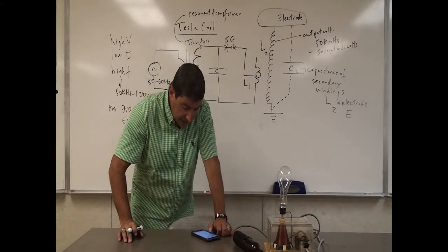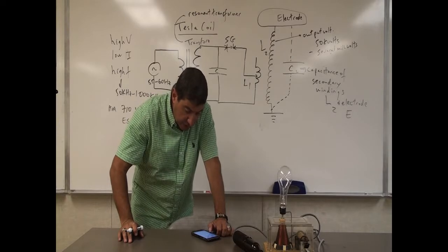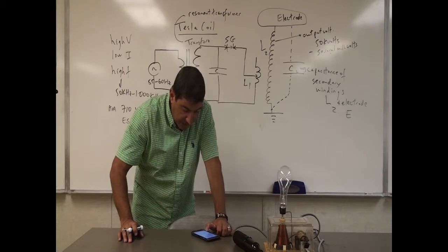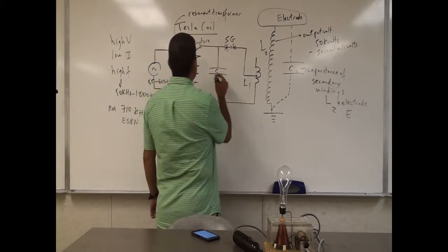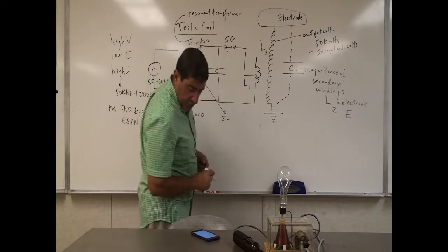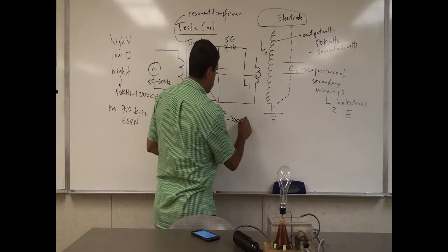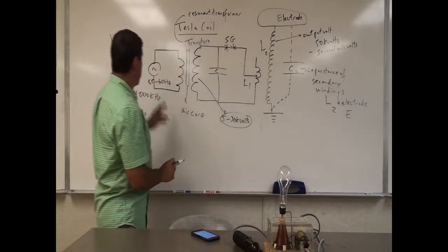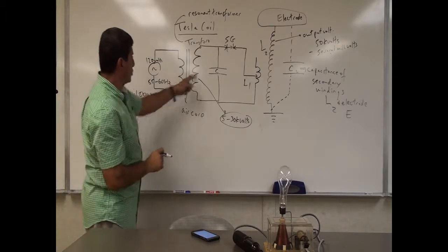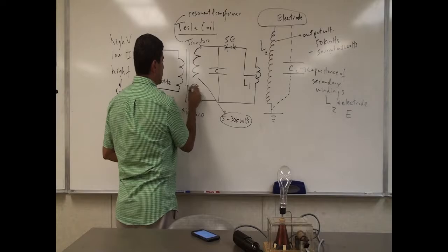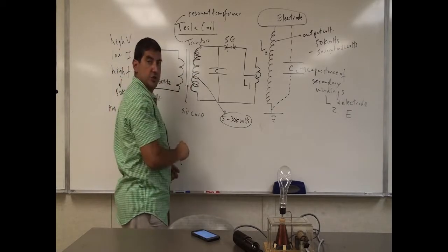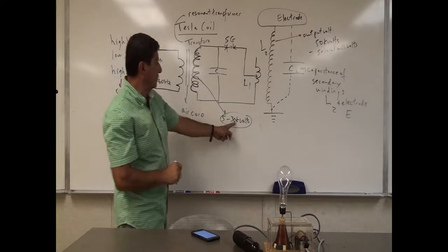So it says a high voltage supply transformer to step the AC main voltage up to a high enough voltage to jump the spark gap. Typical voltages are between 5 and 30 kilovolts. So that means from here to here, we've already stepped up to 5 to 30 kilovolts, all the way from 120 volts, right? So this one must have more turns. When this one has more turns than that, we step up the voltage from 120 to 5 to 30 kilovolts.